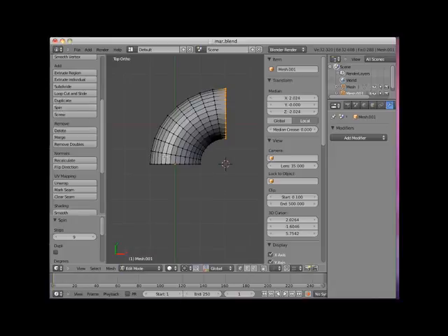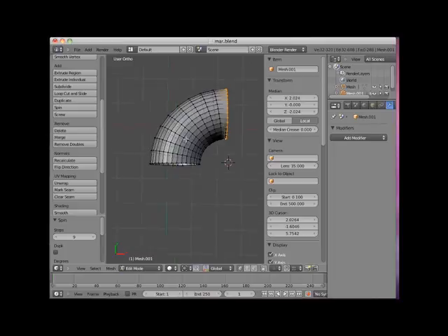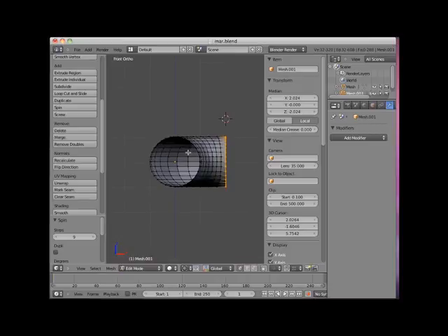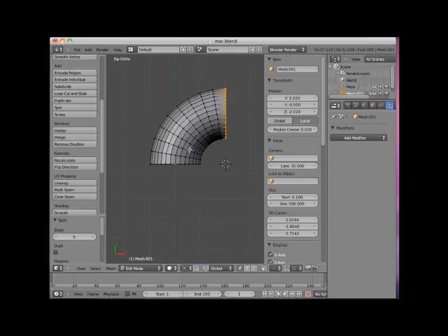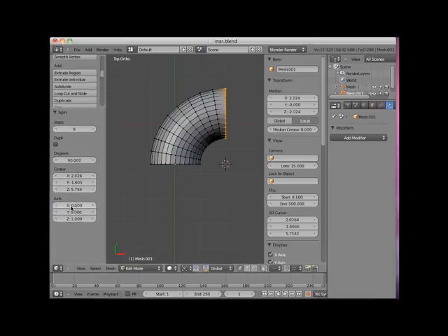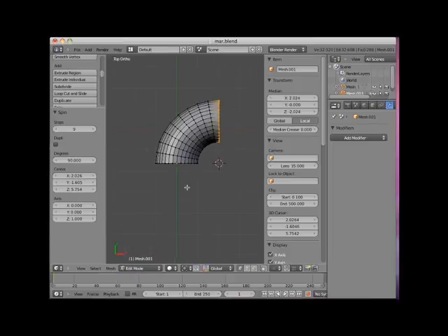As you can see, the Spin tool extruded the circle object vertices around the z-axis using my cursor as the pivot point. Now once the spin extrusion has been executed, the controls for the spin operation are displayed in the 3D Editor Viewport tool panel. By default, Blender spins the sub-object selection 90 degrees in 9 intermediate steps. Notice there are 9 sets of vertices plus the original set.